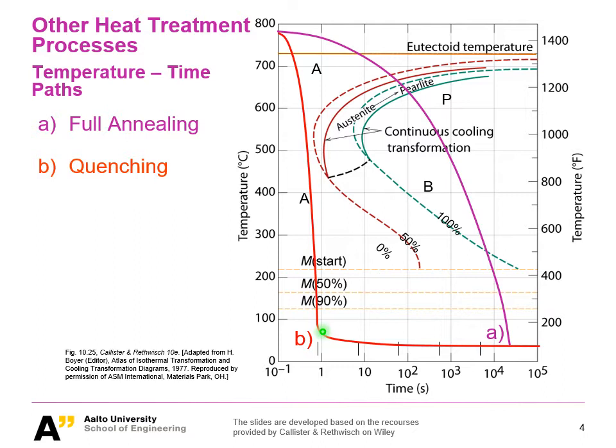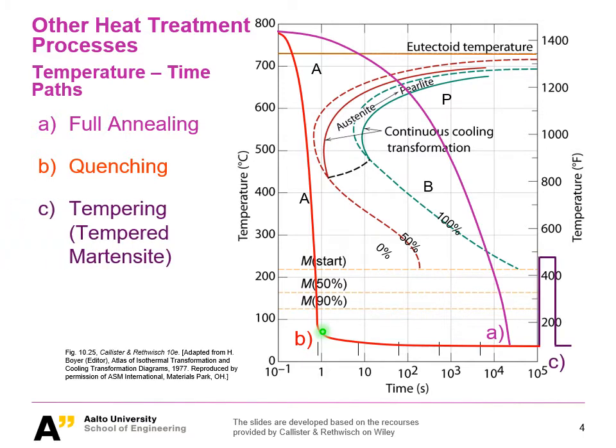That's why it also gives the chance for tempering. If you apply a certain amount of temperature, and increase the temperature above the martensite starting temperature, the material will not be that stable anymore. Due to the very low diffusivity at room temperature, those saturated carbon atoms are trapped in this BCT structure and they cannot go. But when the temperature is high enough and your diffusion is more active, the carbon can easily go away, right?